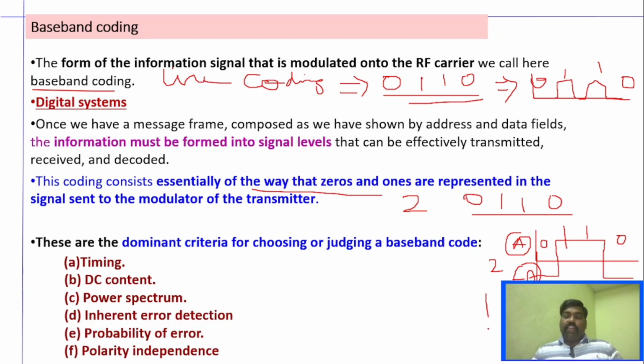There are also other different formats where, say for example, we have a format like this, right? 0, 1, and another. Say for example, if this is 1, and this is 1, and this is 0. And now here, you can see there are 3 signal levels. There is 0 and you have A and you have minus A, right? You have 0, A and minus A. So signal level is 3 here, right? So now you understand what is data level and signal level, and depending upon this data level, signal level, you have other criteria as well.